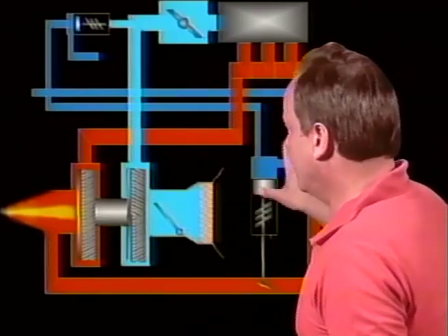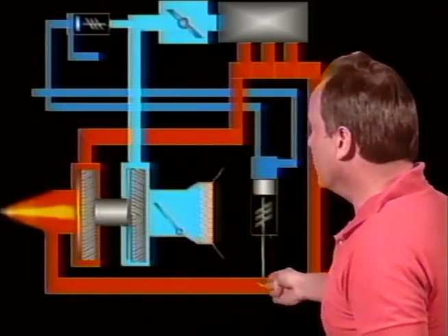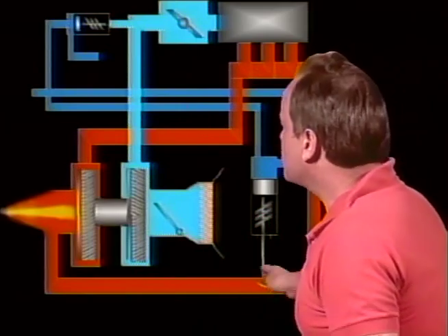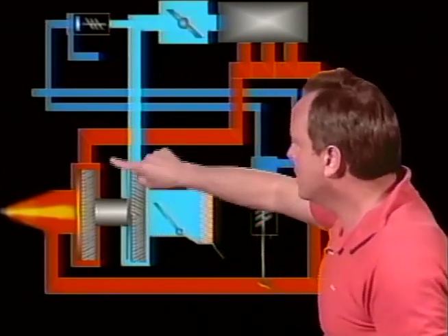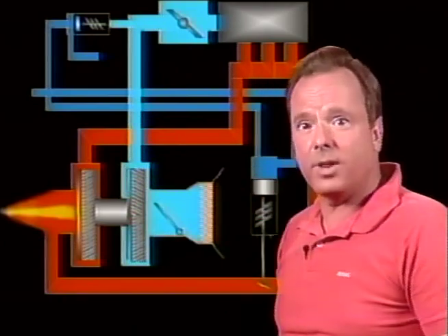All right, now here's what they're going to say also about this. If an engine is equipped with an external turbocharger, and the wastegate is closed, and you take off or start the engine with the wastegate closed, what's likely to happen? Well, if you have this wastegate closed, you've got the turbocharger running like the devil, and you could have serious damage to the engine because of an overboost, because you're directing all of the exhaust gases through the turbine. So if you start an engine with the wastegate closed, you could forget that it's closed, and you could overboost the engine. And that's one of the dangers they're talking about.